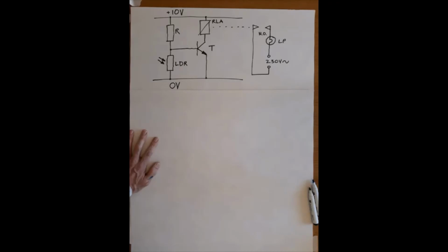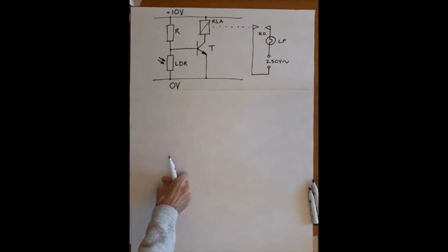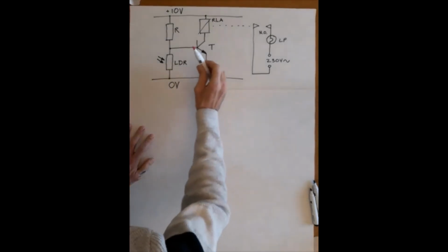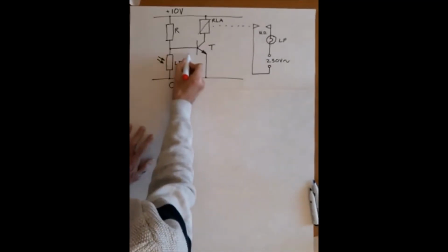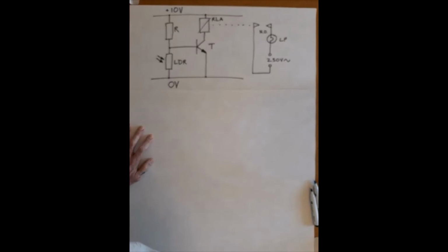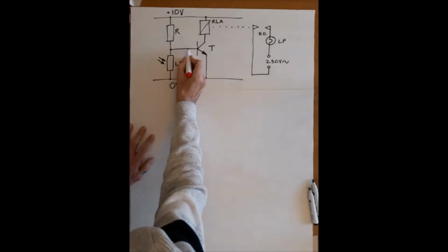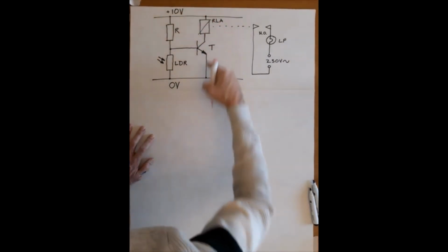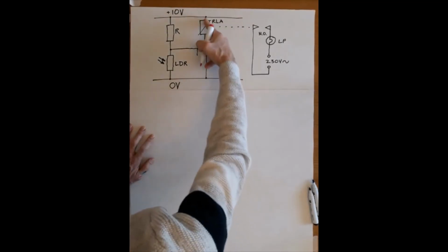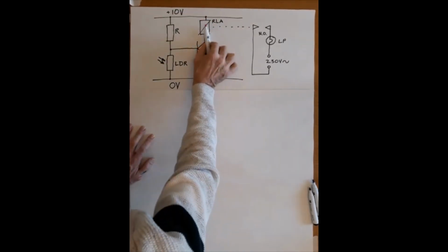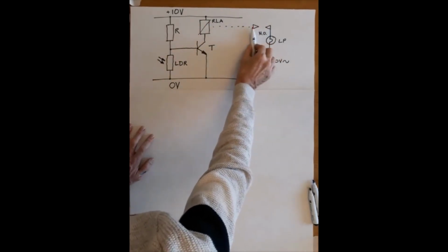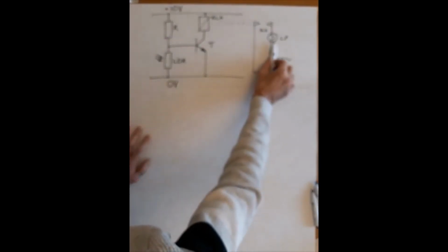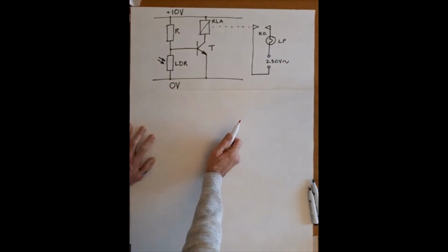So let's have a look at what's going to go on just here. The aim is to get 0.6 volts across the base and emitter and pass a tiny current into the base. If we do that, a current flows from the top of the supply to the 0 volt, so from positive to negative, it flows through the relay coil down to there. The relay will energize, these contacts will close, and we put main supply onto this lamp, so the lamp will light. Just building it up one step at a time.